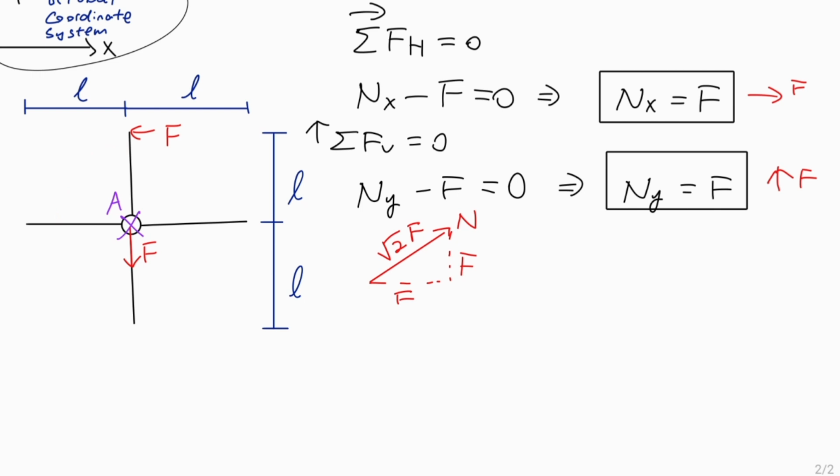In order to make the thing more simple, what I will do is place it on one of the axes, such that only one of these force components generates a moment, okay? I will personally choose right now to put it on the x-axis, so since I'm putting it on the x-axis, my x force points into point A, such that the y force is the only one that's going to induce a moment, and I can just solve it with my y force. I'm going to put my force, say, here, okay? I'm going to put it obviously to the left, because I need my moment to be counterclockwise, okay? And now what I'm solving is the distance I have to put it from this point, which I will call Rx, okay? Let's call it Rx. So remember, this N has a vertical component of F.